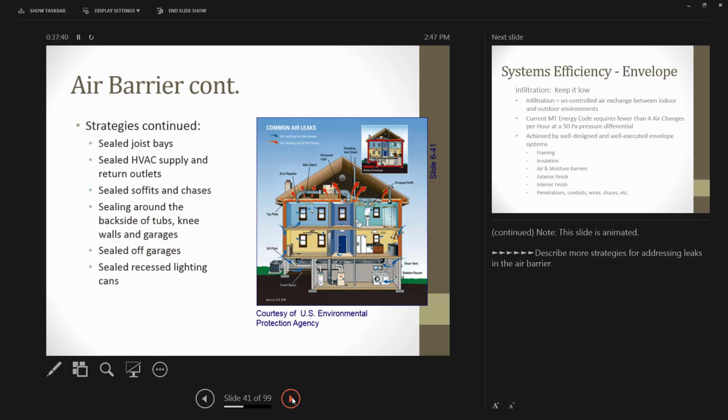They thought they had an R33 wall because they compressed 3 layers of fiberglass into that wall, but they got rid of all of the fibrous properties and air spaces in that insulation, and they may have had an R11, which they would have had with just 1 layer.